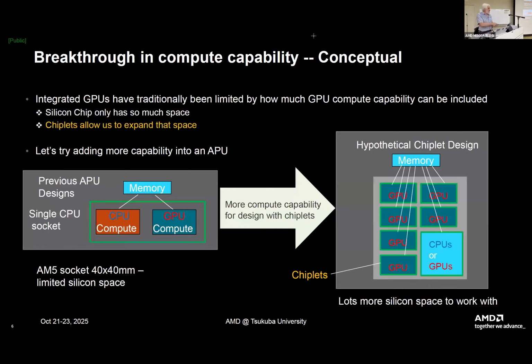We moved to the GPU space with the bigger form factor and several other changes that are very, very critical. This chiplet design. So each chiplet is placed on this silicon base layer. Because if you have to build a large chip like this in one piece, your yield is very low.